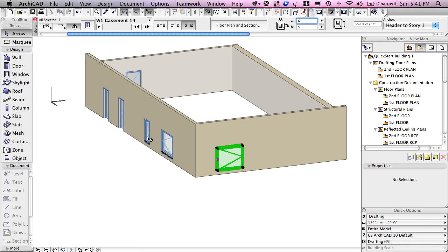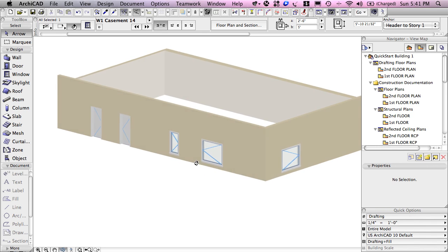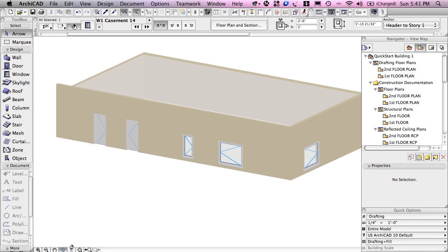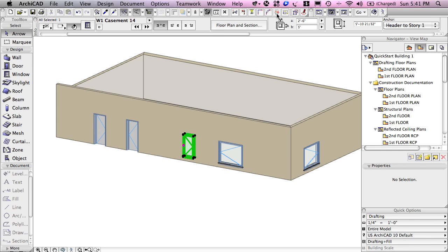Now if on the other hand I think this window, and we'll just rotate, I'll use the orbit command to rotate around. If I select this window here, and let me finish the orbit by clicking again on it, and let me make this window, say, instead of 2'6", let me make it 6 feet. We'll see it got wider in both directions because the anchor point of the window, the insertion point, was in the center. So when you place an element, it is not strictly necessary, but it's very useful to think, what's important? Am I thinking about the center of this or the corner?